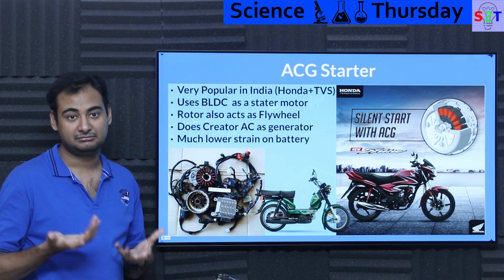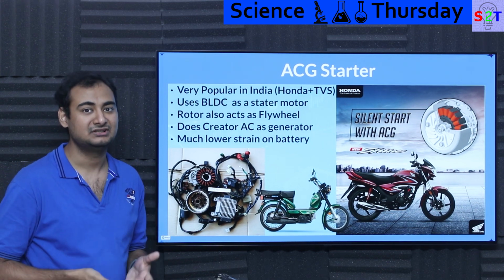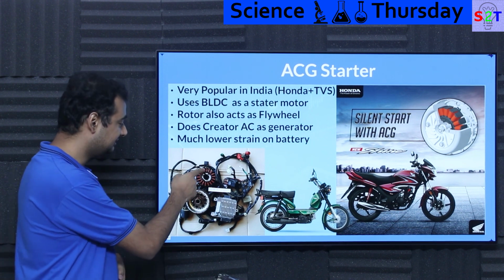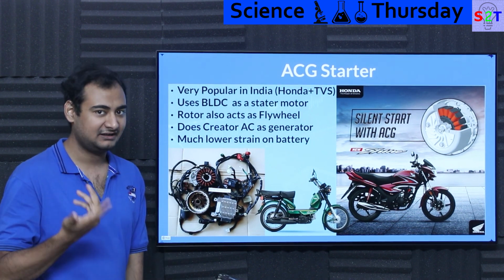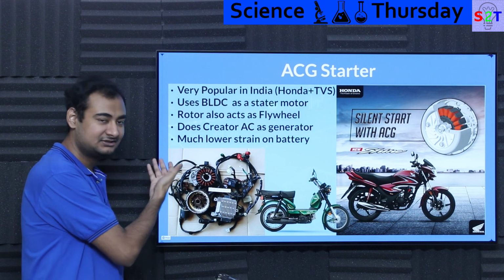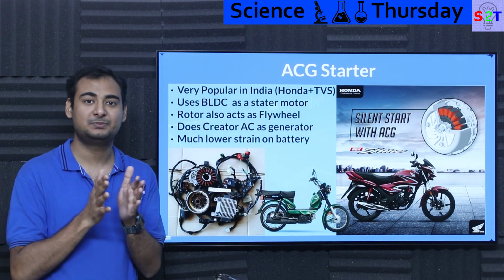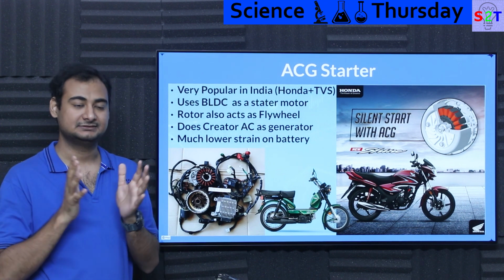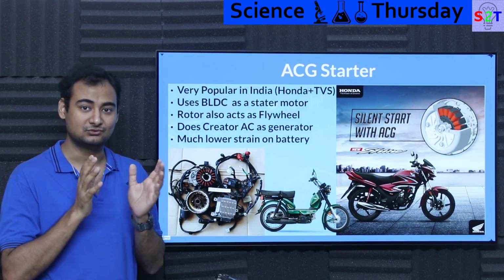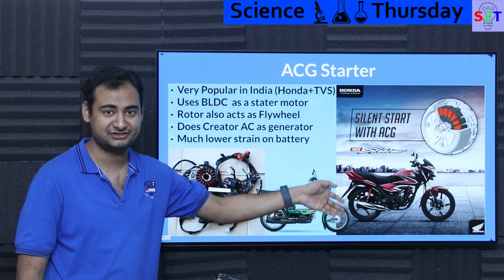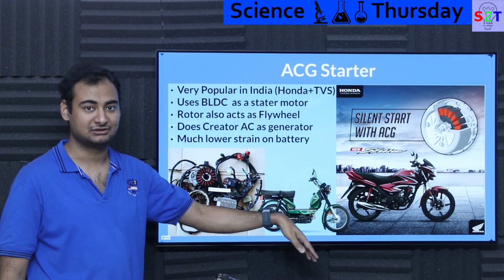And because of the improved engineering, we learned the fact that your engine needs to have a flywheel. Somebody figured out, hey, BLDC has a rotor, you need something known as a flywheel. You need basically rotating mass. Just use the rotor as the flywheel, and that's why it can even reduce the footprint of the system. Your combined mass of the engine goes down. That's why they said it improves efficiency, because dead weight on your vehicle goes down while you are getting higher functionality.